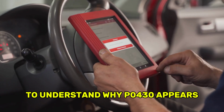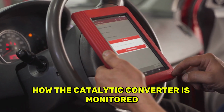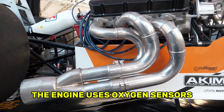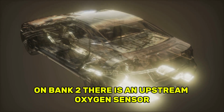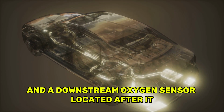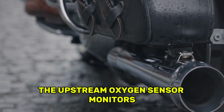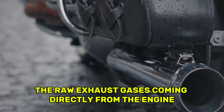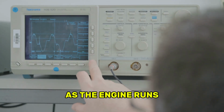To understand why P0430 appears, it is important to understand how the catalytic converter is monitored. The engine uses oxygen sensors to evaluate converter efficiency. On bank 2, there is an upstream oxygen sensor located before the catalytic converter, and a downstream oxygen sensor located after it. The upstream oxygen sensor monitors the raw exhaust gases coming directly from the engine. Its signal constantly switches between rich and lean as the engine runs.